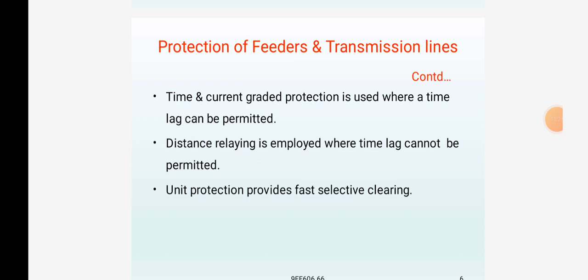The check relay is an earth fault relay energized from a current transformer mounted in the incoming transformer neutral earth connection. The contacts of the check relay and frame earth leakage relay are in series, so that the independent relays must operate before the trip circuit is completed.